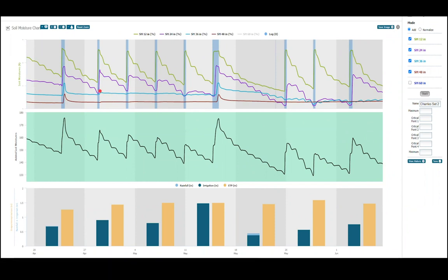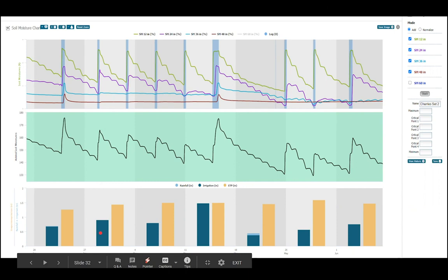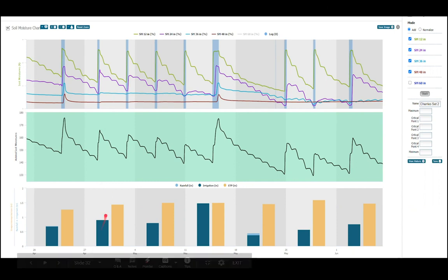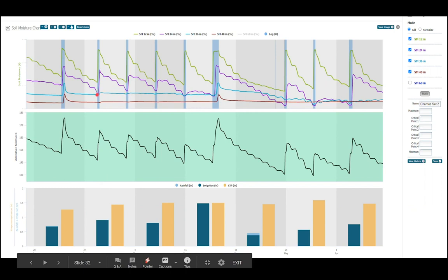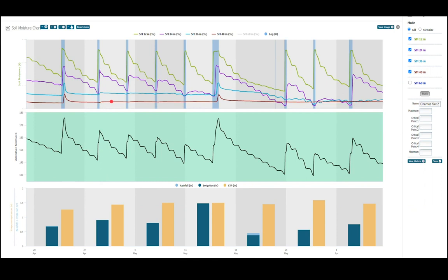And then we can see that he switched that irrigation strategy to 2 times a week, with shorter durations. It's still irrigating during the week, 0.7 inches, 0.8 or 0.9 inches, but in 2 events, not in one. So we can see that the water hits my 3rd foot and the moisture content stays flat on my 4th foot. So by that trial and error, he determines how long he needs to run in order to reach the exact depth that he wants to reach with his irrigation events. Here we can see that this was at the beginning of the season, and we had a lot of root activity on the 1st and 2nd foot, not a lot on the 3rd. Some root activity started happening during May, and now here at the end of May, clearly the 3rd foot sensor is showing clear activity.